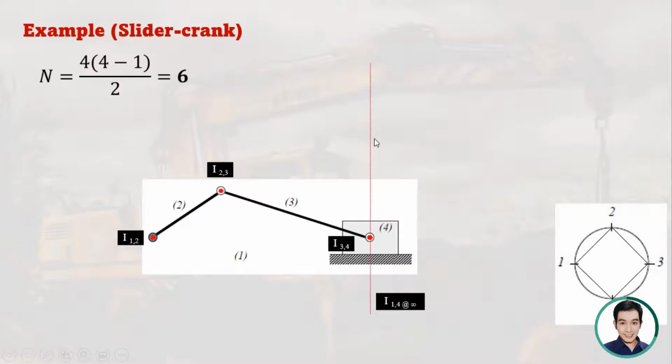So now that we located 4 out of 6, we need to find the others. So first, the IC 2, 4. Just like before, the adjacent to 2, 4 is 1, 2 and 1, 4. Because 1, 4 is infinite, the connection between 1, 2 and 1, 4 will also become infinite.